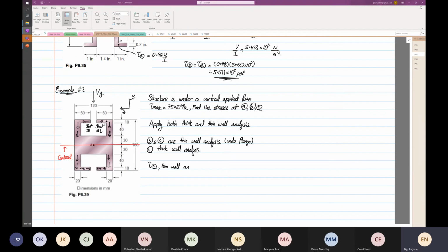It's going to be based on wide flange, and we are going just 1Q, right? If it's box beam, it's 2Q. So we are just going to consider this area down here that I've drawn in dark. Again, Q at point C is equal to width times depth times y bar. So the width will be equal to 30.